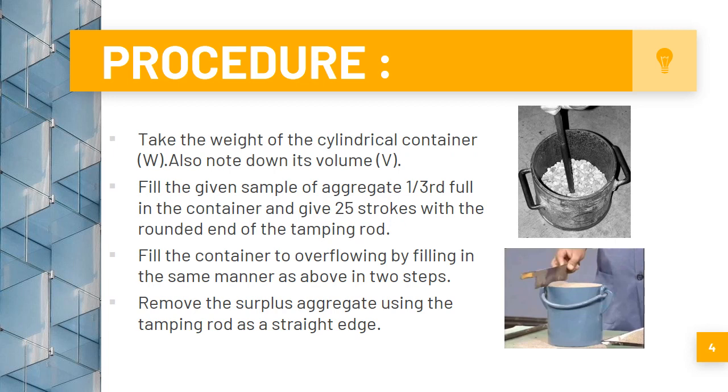Next, we fill the given sample of aggregate until it's filled to 1/3 of its capacity, and we give 25 strokes with the help of the tamping rod. We must ensure that we are using the rounded end of the tamping rod here.